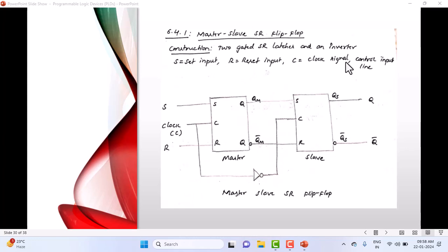As long as the clock remains 1 here, the S and R can be anything. It can be useful data. It can be not useful data also. It can be noise also. That's a problem in industry. Whenever we use level trigger, noise can propagate. S may be perfect, but sometimes some noise may come with R. Or sometimes R also may be perfect, and some noise may interfere here. That will create a lot of unwanted signals in the entire memory, the flip flops.